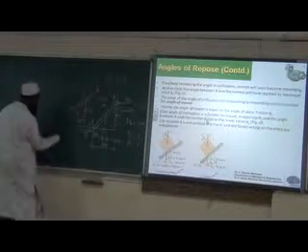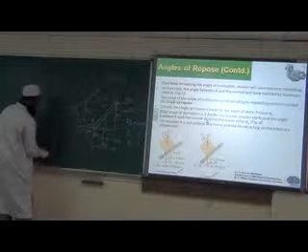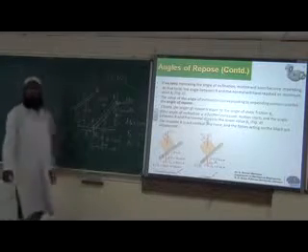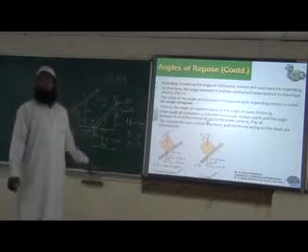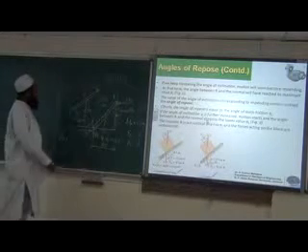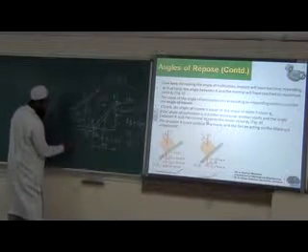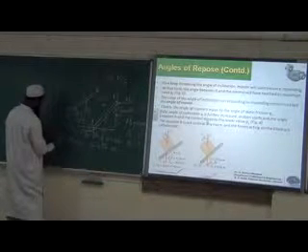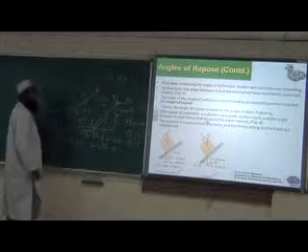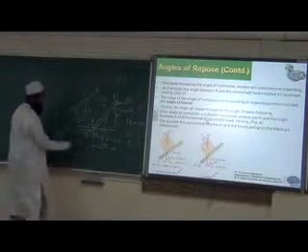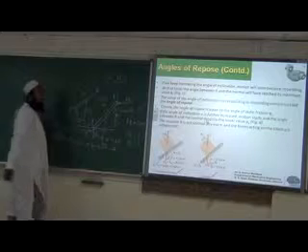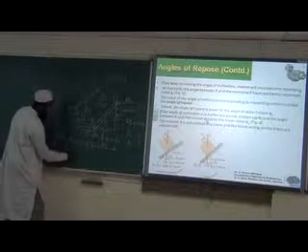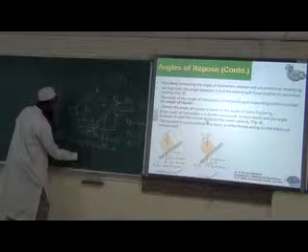Now you consider the forces acting in the y direction. Use the equilibrium equation: we sum up all the forces acting in the y direction. We have only two forces, NF and W. I have assumed upward force as positive. The sum will be equal to 0, the equilibrium condition. So NF will be equal to W, that is 15 Newton.